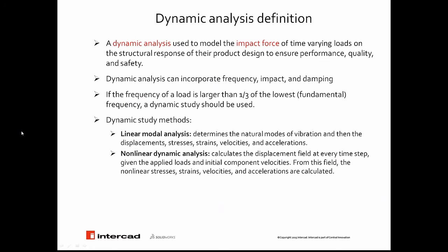We can incorporate frequency, impact, and dampening in this type of study. When we run a frequency analysis and find that the frequency of the load is larger than 1/3 of the lowest or fundamental frequency, the dynamic study needs to be taken. We have two different methods to take the dynamic study.